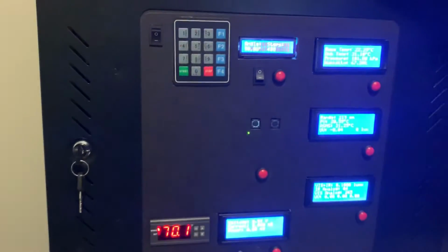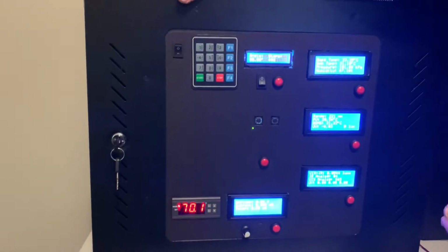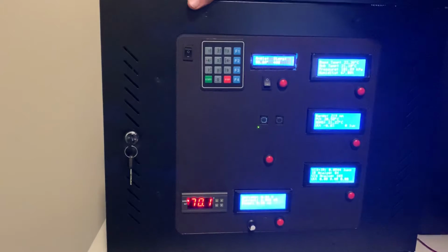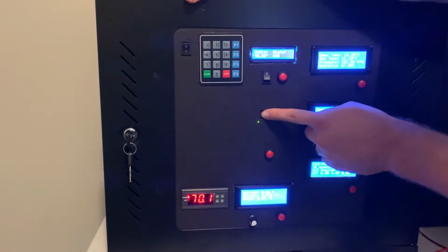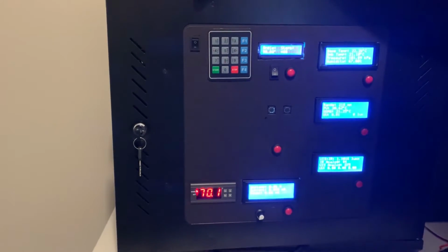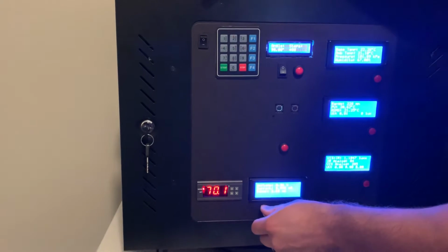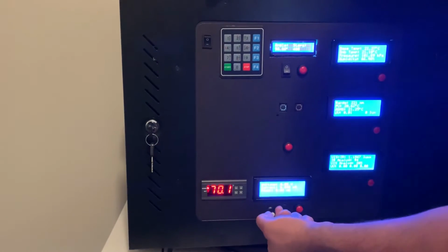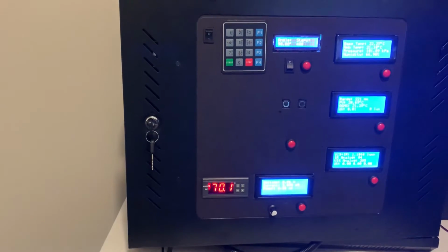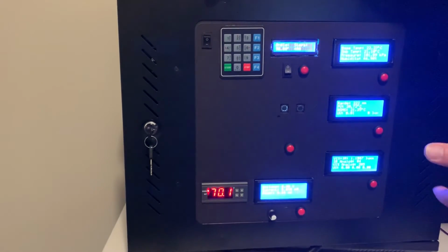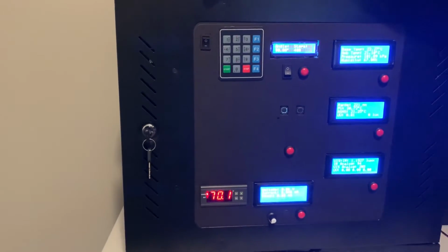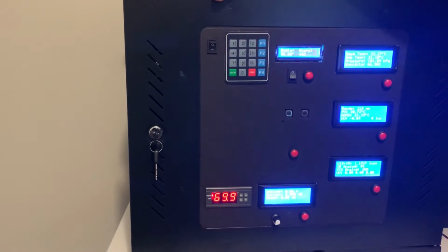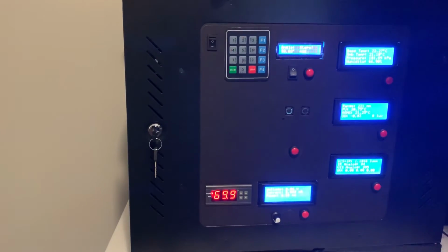It'll go between red, green, blue, white, ultraviolet, and IR, and then back to itself. And then I can subject it to red first, and then use this switch down at the bottom with my PCMS. It's just a potentiometer, and it serves as a variable resistance to the photovoltaic array so that I can gain typical PV and IV curves by increasing that resistance.